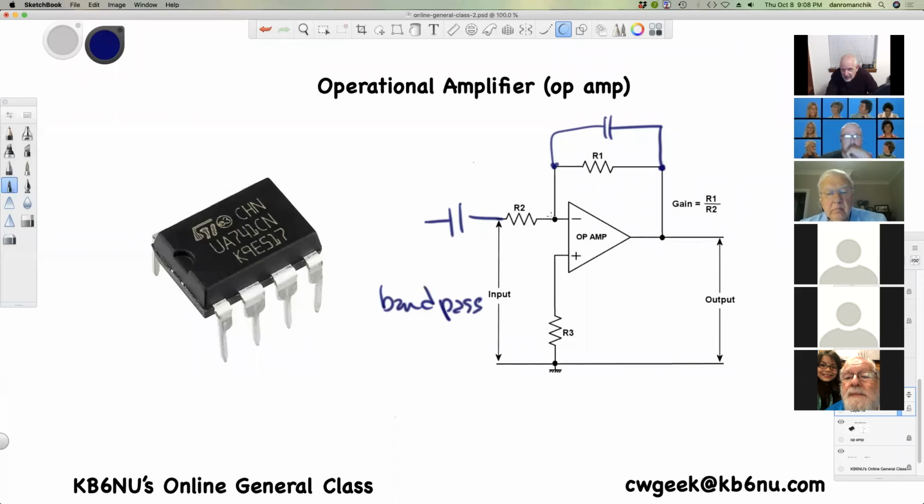What you do then is you figure out what the impedance is of this and the impedance of that, and it's the impedance of this circuit over the impedance of that circuit. And if you go through all the calculations, which again, took like a week in engineering school, you'll find out it's a bandpass filter. You can go online, and in fact, that's what I did to make sure I got this schematic right.